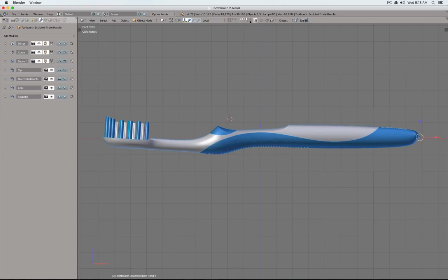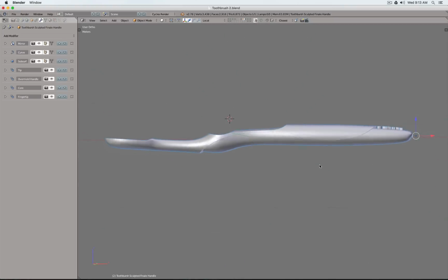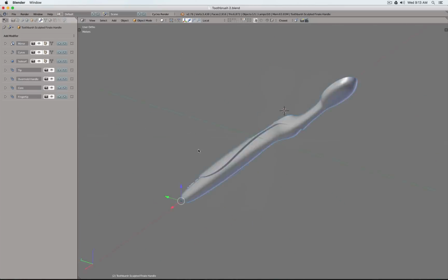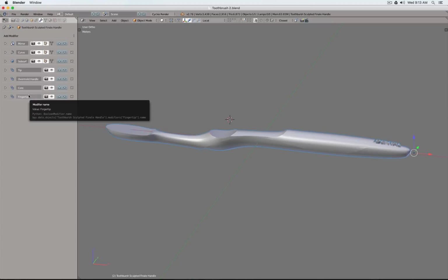So first, let's take a look at what, for example, we would have to bring over to Fusion. So this is kind of like an end result of the mirror command with the bend, the subsurface, and then the different trim commands or Boolean commands. So for example, these Boolean commands, we will completely rebuild from scratch in Fusion. So this type of a mesh, this end result, we do not want to bring over.